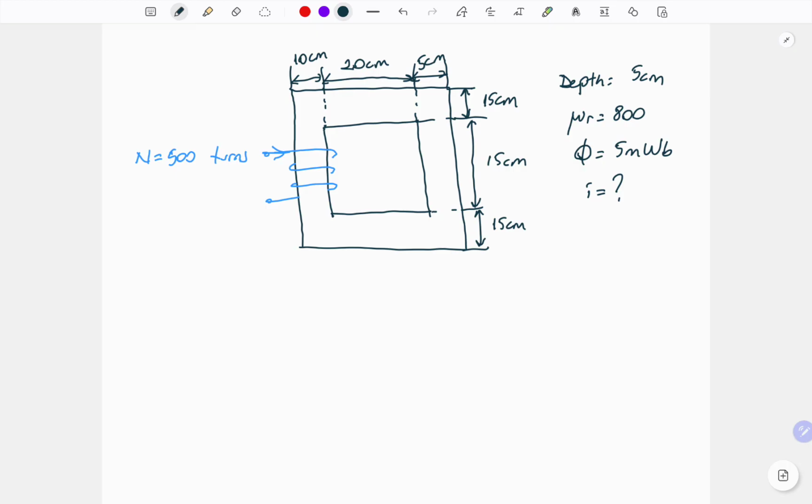How will we start? The first step should be to determine how many sources and how many reluctances we need to use to describe this figure as an equivalent circuit. The source part, I think, is easy, because according to your supplied windings, you can determine the number of sources. In this figure, we have only one source, on the left leg. And according to the current direction, we can also determine the source polarity.